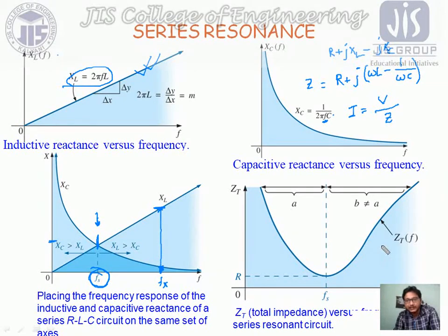And similarly, this is the overall impedance. As we know, whenever we change the frequency, our XL and XC change, but our resistance is fixed. At the resonance point, when XL is equal to XC, our impedance Z will be only R. It means the inductor and capacitor effects nullify each other, so this part will be 0, and our Z will be only R. Previously our impedance was R plus something, now we are getting Z equal to R.